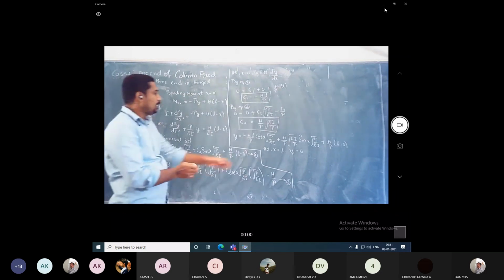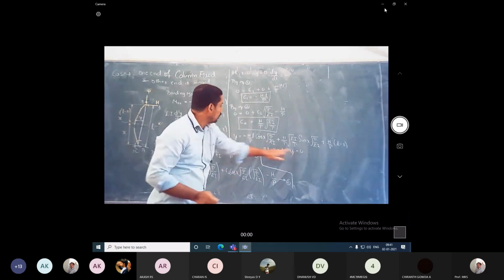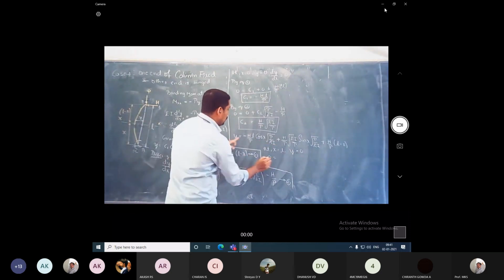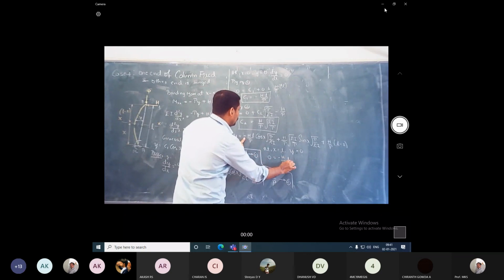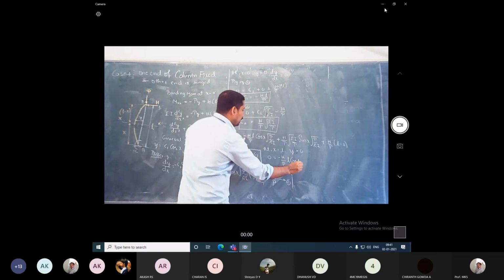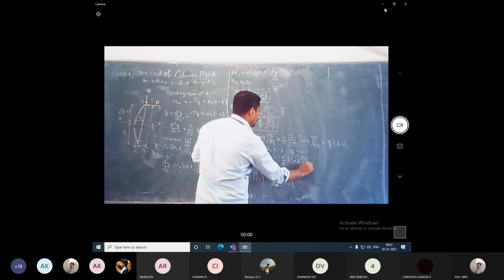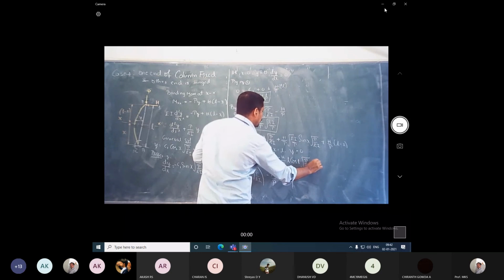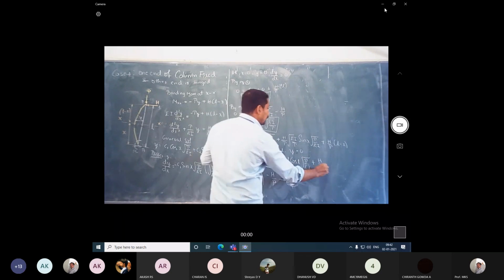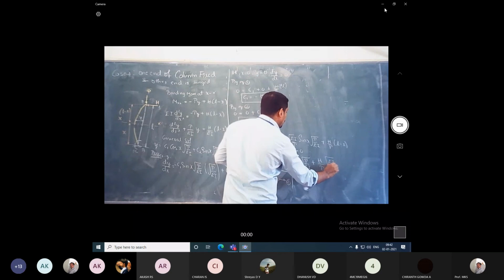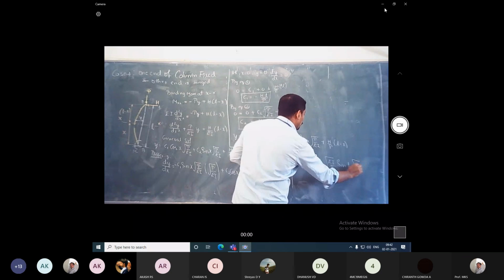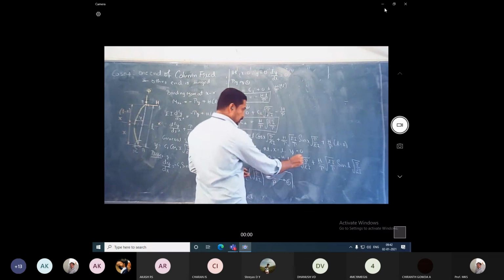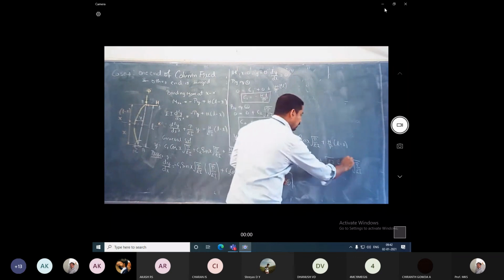Okay. So you apply this, this will be reduced. So when y is equal to 0, x is equal to L: 0 = (L - h/p) L cos(L root(p/EI)) + (h/p) root(EI/p) sin(L root(p/EI)).